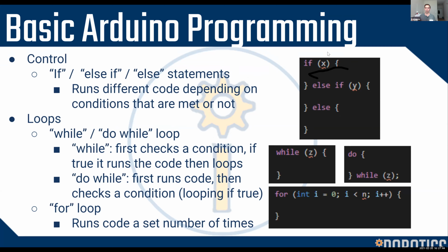generally works. You can leave out the else if part, you can leave out basically any part of it you want. You can just end it after the first block if you just want, if a pin is high, to increase a counter, or send a character over serial to the Raspberry Pi or something. And then you can do, if the pin is high, I want to send a voltage out through analogWrite. If it's not high, I want to do something else. You can leave whatever pieces of this out that you want to get whatever logical functionality you want.